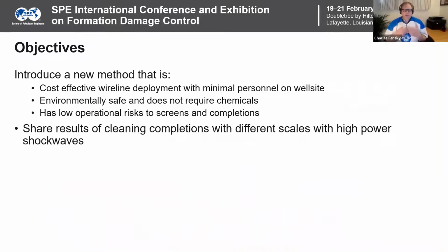So the objective today is to introduce a new method with high power shockwaves that is cost effective with a simple wireline deployment and a service that requires minimal personnel on site, often only one person. This method is environmentally safe and it doesn't require any use of any chemicals being either brought to well site or having to be managed on that well site. This method also has very low operational risk to sand screens and completions. So now I'd like to share the results of cleaning those sand screens and completions with high power shockwaves.